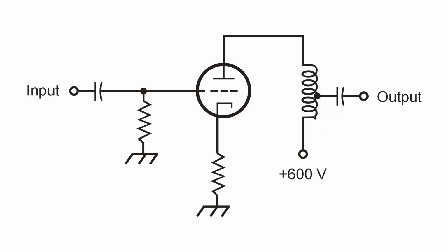But those are the functions of the components of a simple triode radio frequency broad-banded vacuum tube amplifier. If you place a capacitor, a variable capacitor, in parallel with this coil, you can get resonance at the frequency that you desire, but you also run the risk of the circuit breaking into oscillation. So I hope that outlines for you basically what the functions of the individual components in a simple electron tube or vacuum tube triode amplifier do. Triode again, 3 elements. Triode means 3 elements: cathode, control grid, and anode or plate.